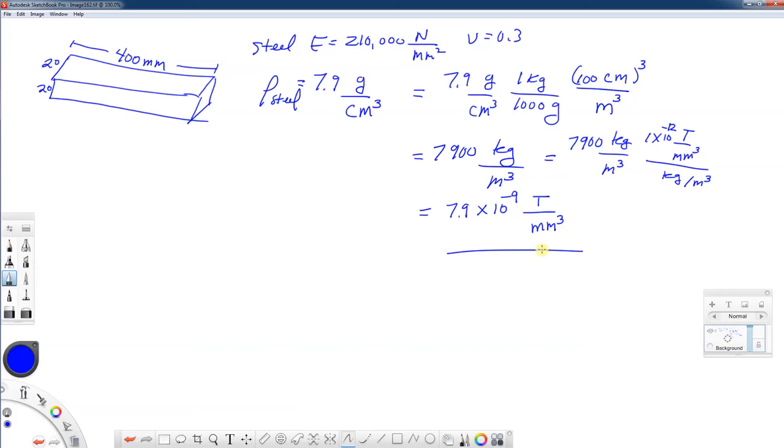The other thing we want to do is we want to take a look at the analytical solution for the natural frequencies of a beam. And these involve solving partial differential equations and using some tables that you can tabulate these different values for. There's different places you can find this, but the place that I'm going to share with you is a table from Roark's formulas for stress and strain.